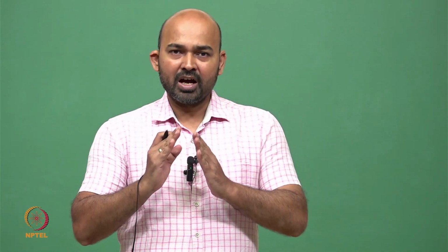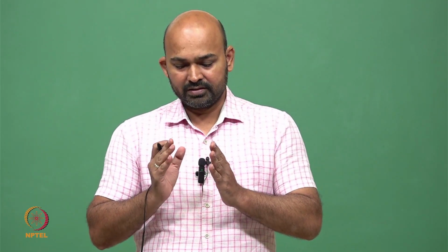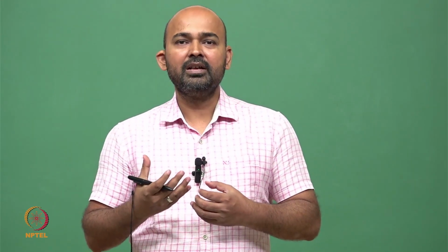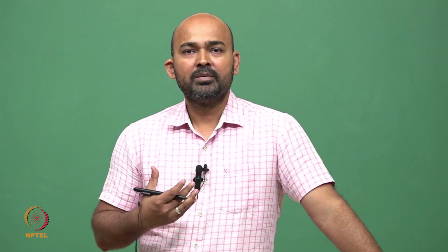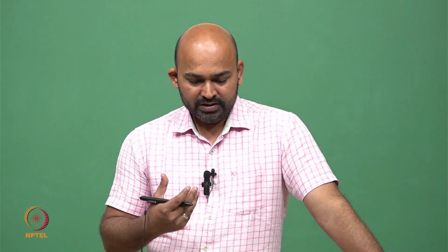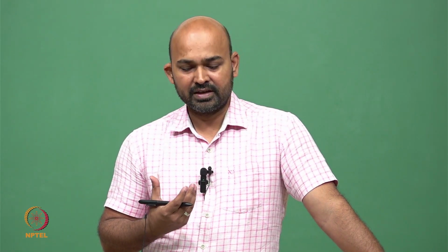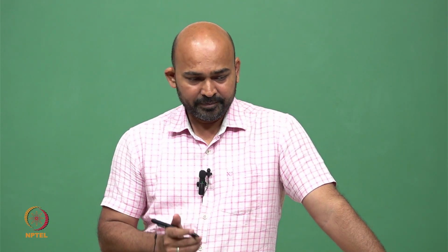If we have a very sharp change in the impedance of this resonant circuit, it is very easy to detect by electrical means, and it is desirable for making a sensor. So this high value of quality factor is desirable to make a sensor, any kind of sensor, in fact, not only the temperature sensor.